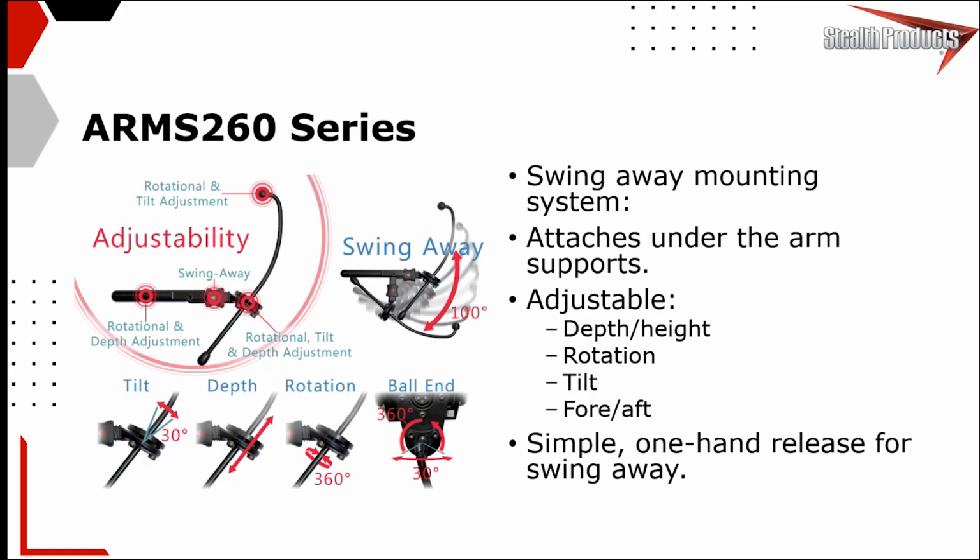The rod is sprung steel, so it can start to move and stretch a bit if there's a lot of weight on the end of a long rod, for example. And so we want to see this tucked in as tight as it can be for any given application. We always like to see that this excess material gets trimmed down as well so that it can fully flip away and it's not drawing lines in people's drywall and things like that. We don't want to see that cause problems.